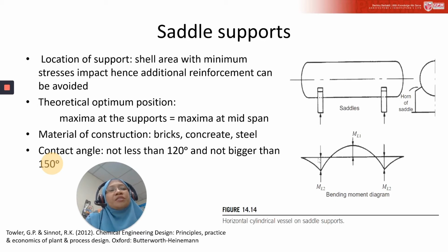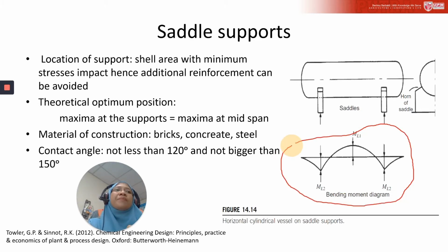This shows the distribution of the longitudinal bending moment. The maxima of this bending moment occurs at the supports, this is the support, and at the mid span.